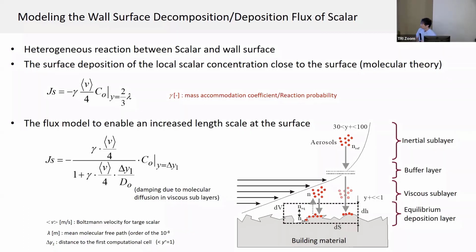In this case, is the deposition flux defined by the air phase concentration only, without discussing the surface concentration? If this is diffusion flux, generally speaking, we must consider the potential difference, the gradient of concentration. But in this model, the information of surface concentration is indirectly integrated into the gamma value. This means the concept assumes a hypothetical zero-concentration surface and maximizes the concentration gradient in the vicinity of the wall surfaces.